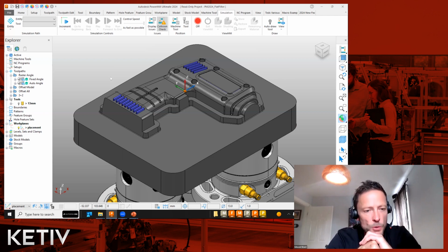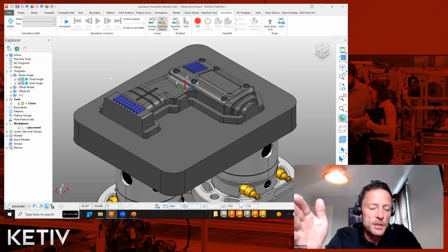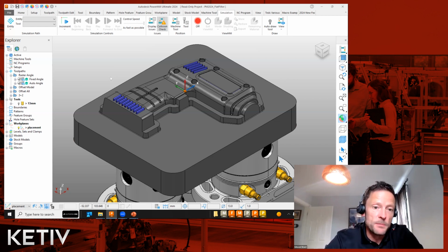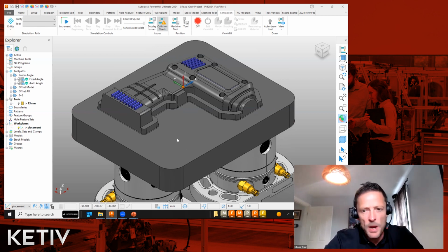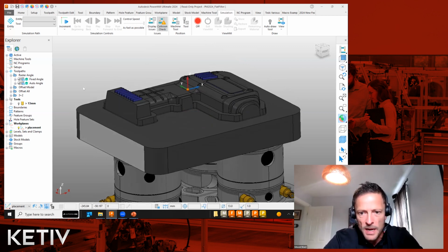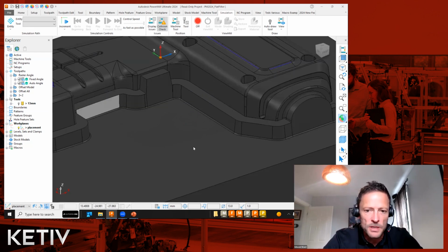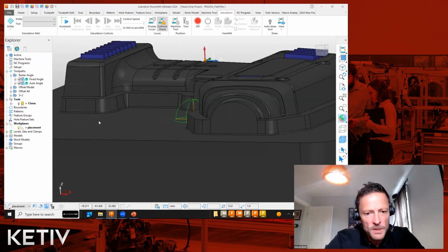But again, multiple toolpaths. Now, with the inclined flats, it allows me to define a start range and an end range of angles on your machine. I'll show that last, but if you needed to, we could machine that flat there, the side of the part. Now this would probably be squared up beforehand, but you may have multiple flat areas within the part where, obviously, some are reachable and some are not. So that's down to PowerMill to decide whether it can get into those areas.